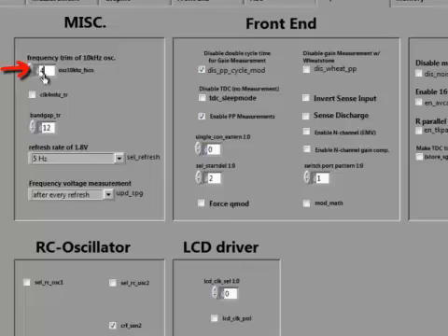In normal cases, please do not alter the settings of these bits. However, when you are driving an external LCD controller with the LCD clock from PS09, then you might need to adjust these trim bits to get the required LCD clock frequency.